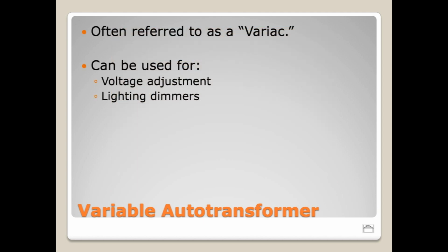Lastly, in this same voltage adjustment category, again, if there's anybody who plays tube guitar amps, or let's face it, you're all going to work with people who play tube guitar amps. If you have an older tube guitar amp, you can actually modify the tone a little bit by adjusting the voltage. So some of these guitar amps really love to work at exactly 115 volts or 120 or 110, right? You'll see this kind of rated on the back, what's coming in on the cord. It'll say it's designed to run on this voltage.